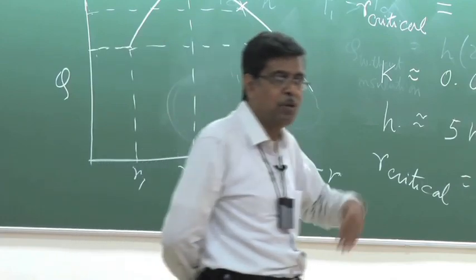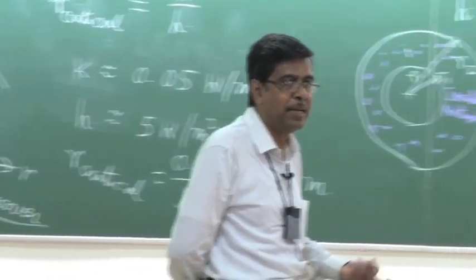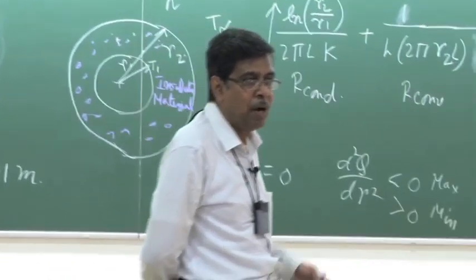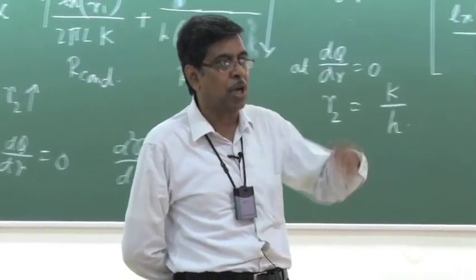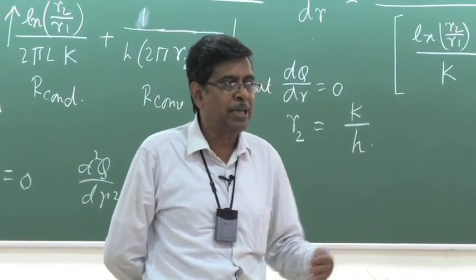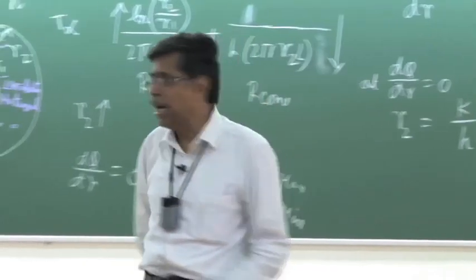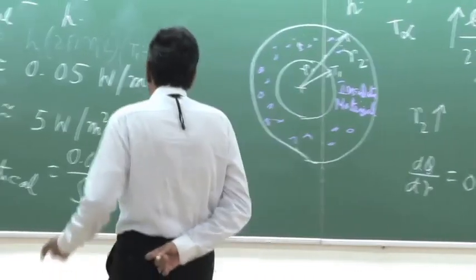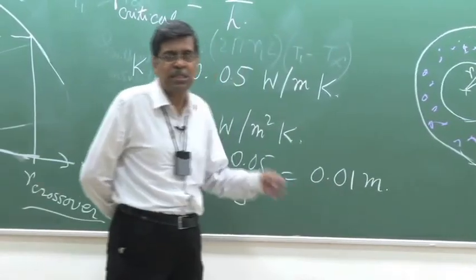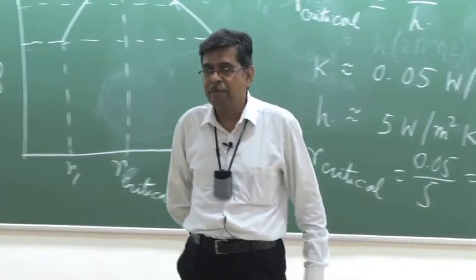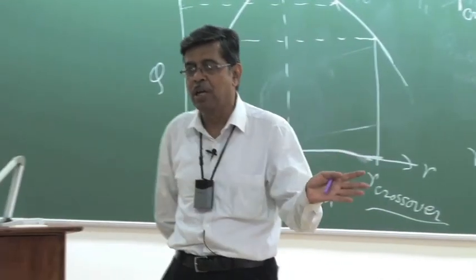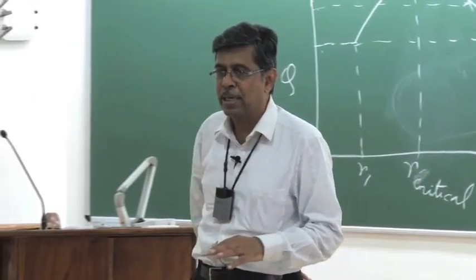Afterwards we will see, when we do the scaling analysis, we have already done it in the fluid mechanics class. How do you scale things? You can understand the order of magnitude analysis. A parameter can attain a maximum of this value. So therefore, if I ensure that my critical radius of insulation is much more than 1 centimeter, I am happy that it has definitely gone beyond the crossover radius.